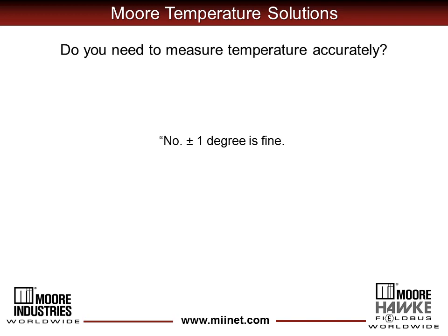And that response is actually quite helpful in that it tells me that this group really doesn't appreciate how difficult it is to measure temperature to that degree of accuracy. Plus and minus 1 degree in a process environment is a high accuracy temperature measurement. And you have to do everything right if you're going to get close to that degree of performance.